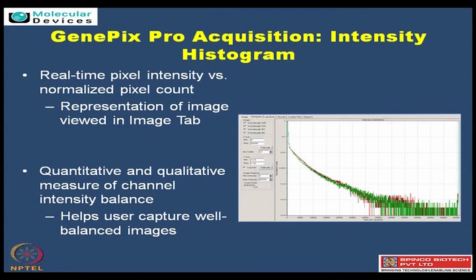Once you are able to do that, you can see and select whether this PMT is good for you. This is a way you check which PMT is more suitable. You select a PMT, look at the overlap, and wherever there is the best overlap without saturation, you want to go with those settings.